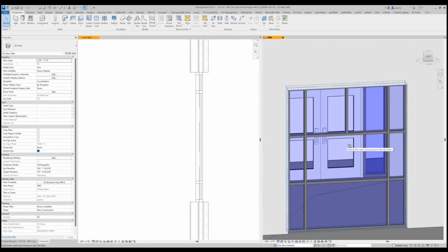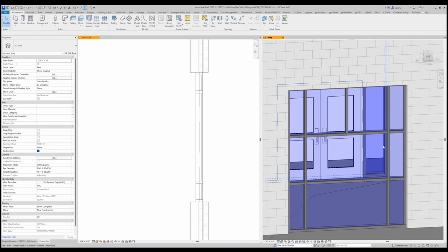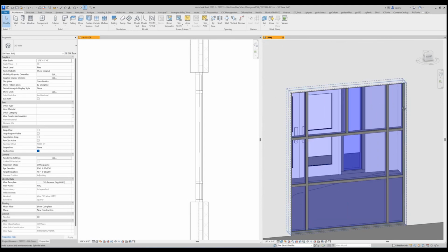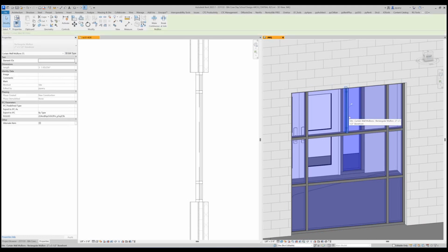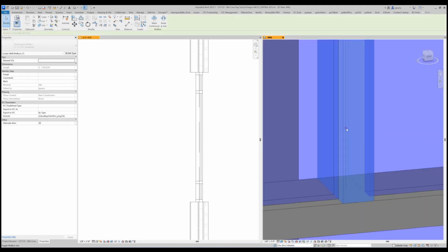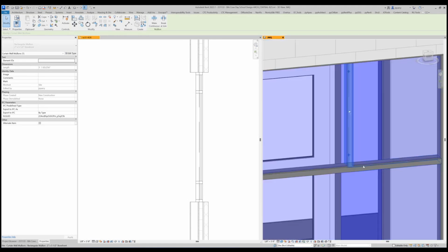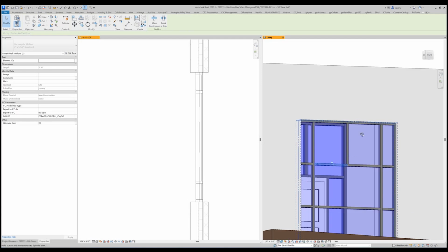This is a very simple point that not a lot of Revitters remember to deal with. How did you change the order? There's this little icon right there. You just click it to toggle the mullion join. It's like a wall join, but for mullions. And I could have done it from any of these, it doesn't matter. It can only go one of two ways.